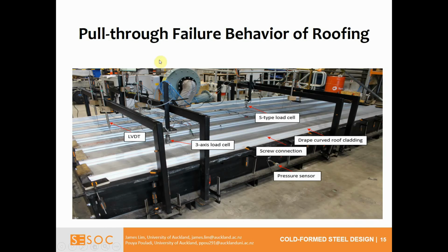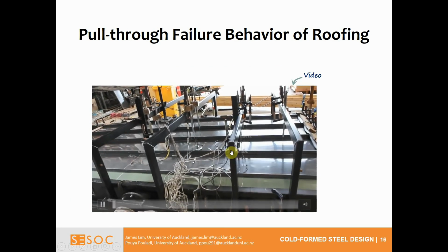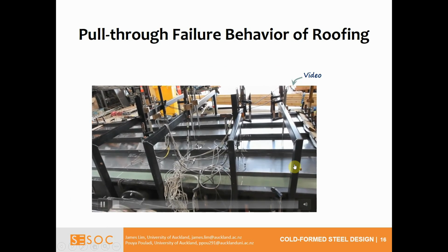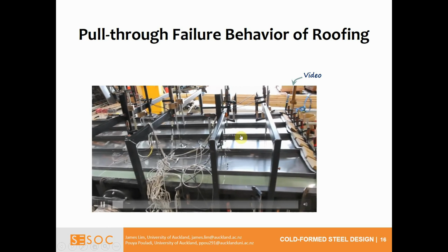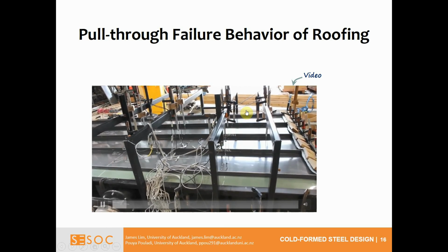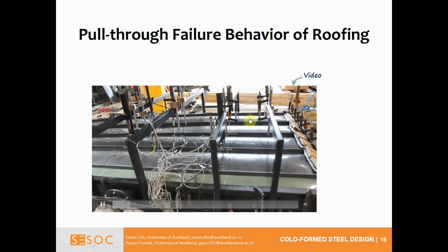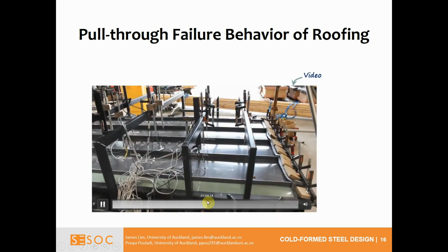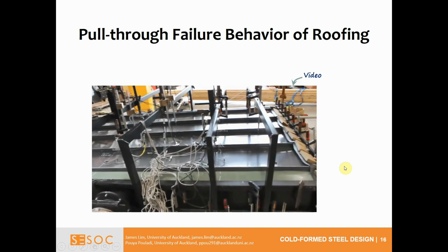Some other work that we've been doing is for roofing profiles. Here you can see a roofing typically used in houses in New Zealand, and then we'll be doing some pressure or suction tests, pretty much looking at how the screws fail in these members under cyclonic loads. Right here you can see one of the tests that's been done at the university, and as I said, we're sucking and pushing the air back into it, and then looking at the failure of the screw at the end of, say, 1,000 cycles.